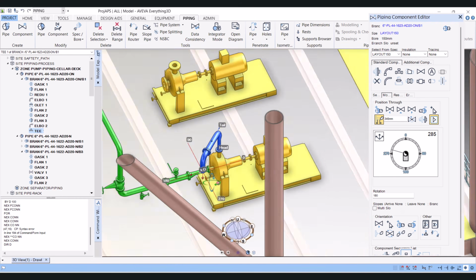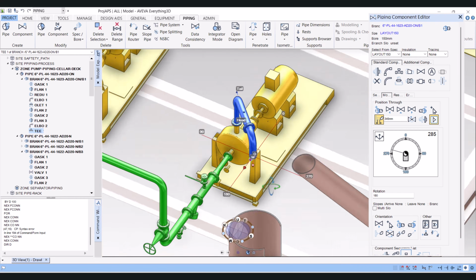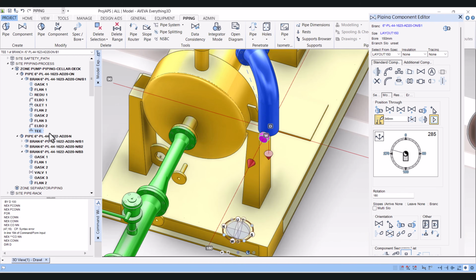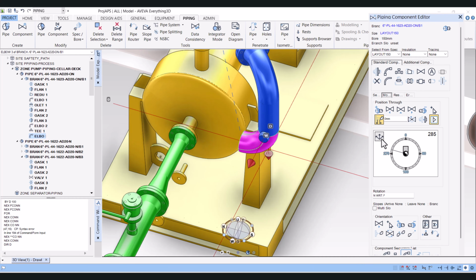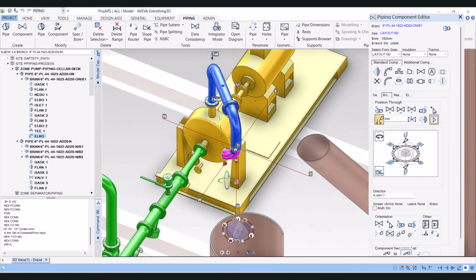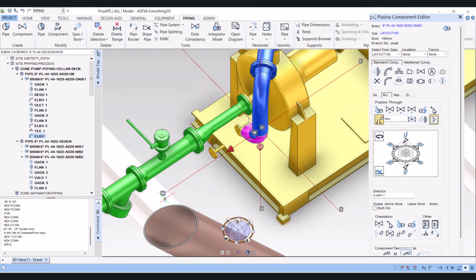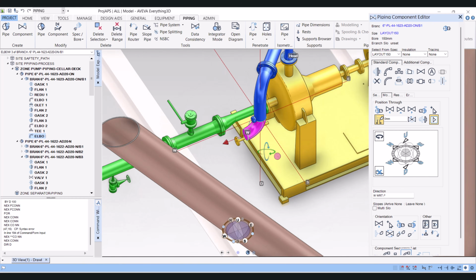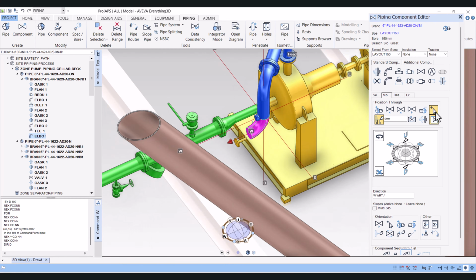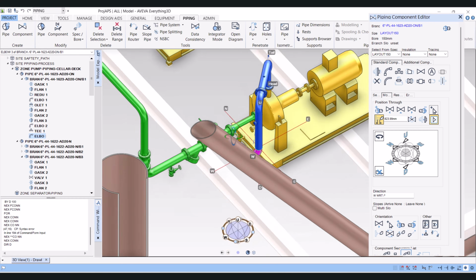and the drain connection should be in the horizontal. Now we have to create elbow. Click on modify, click on this UCS. This side is west. We have to click on west. The direction will change. Now click on this arrow and click on this element and select this pipe, so the center line will match.